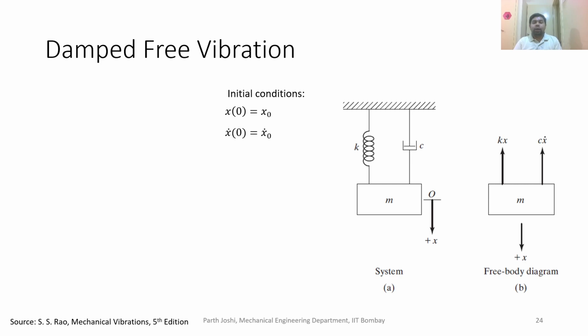Okay, yes. To derive the differential equation, in this case it's a simple mechanical system, so we can simply apply Newton's second law. Mass into acceleration is the sum of the external unbalanced forces, and the external unbalanced forces for this mass are just the spring force and the damping force.